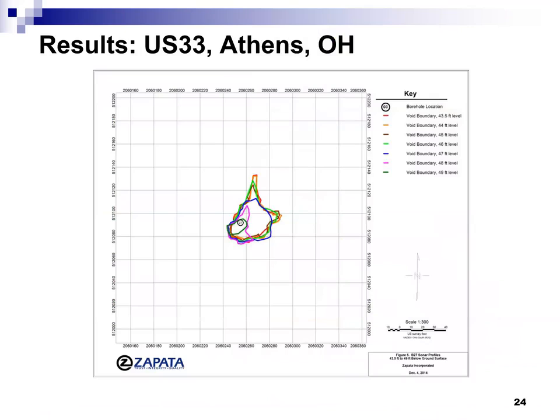So here is the void from 43 to 49 feet in depth, with a different boundary at different depths. So it's quite large with depth. Some locations are like 40 feet in length, 40 feet lateral, but very shallow, very thin in the vertical dimension. So very thin void. We found that we can go up to probably 3 diameters of the void with the depth. So if you have a 10-foot void, we can identify down to 30 feet in depth. Deeper than that, we don't see it very clearly, but we see a soft material joint. So we can still identify probably down to 5 diameters in depth.